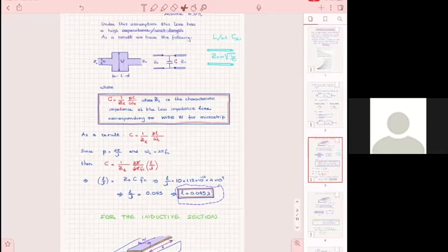And that's why it looks like this in microstrip. It looks like a section of line that has a wider conductor from, of course, the 50 ohm lines that feed it, because you have one 50 ohm line here and another 50 ohm line there. But this is much lower characteristic impedance, 10 ohms. So it's much wider W. Okay, then I found that length.